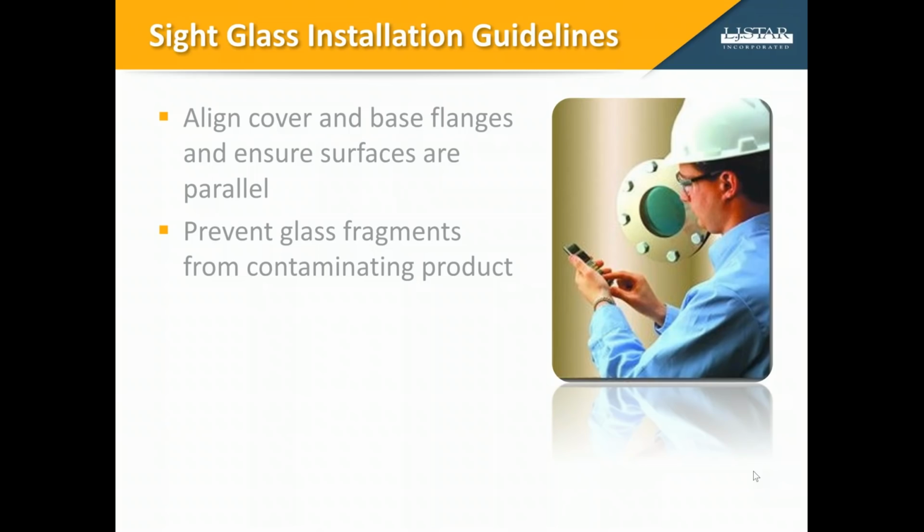When installing quartz sight glass discs, follow the manufacturer's instructions carefully. Quartz should never be used without the appropriate holder. Putting quartz under compression outside of its holder may result in cracking and failure.